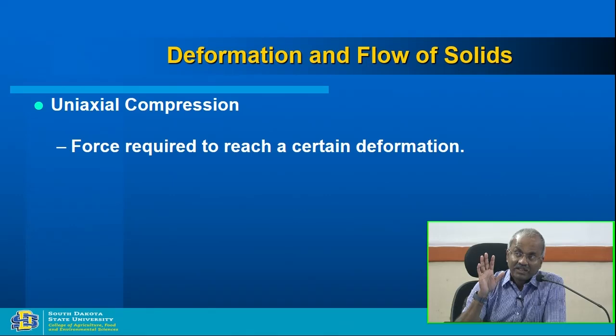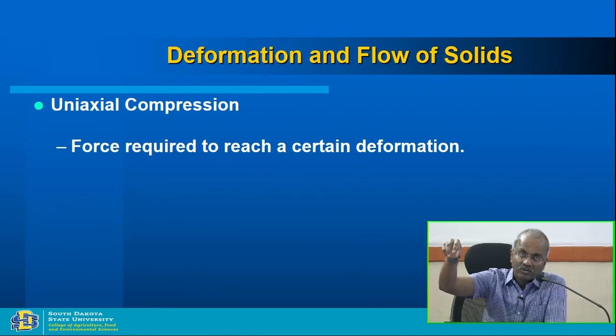Follow me? On the other hand, if you have material and you put only a small amount of force, a small amount of load on top of that, what happens that time? It's a constant force you are applying and you are going to measure the deformation. So when you put the constant force, the material will start flowing slowly and then it will stop deforming after some time. And from that measurement, that's called creep, material creeping with the constant force. We will be talking about that also.